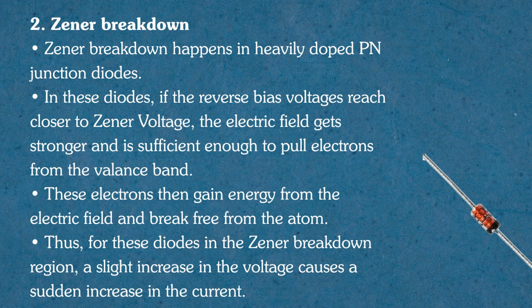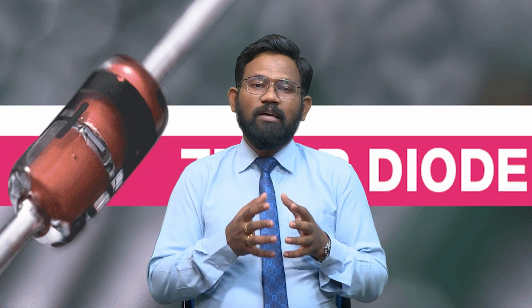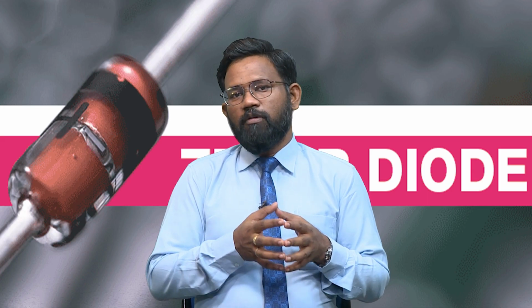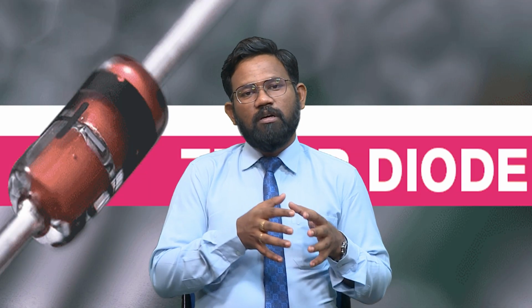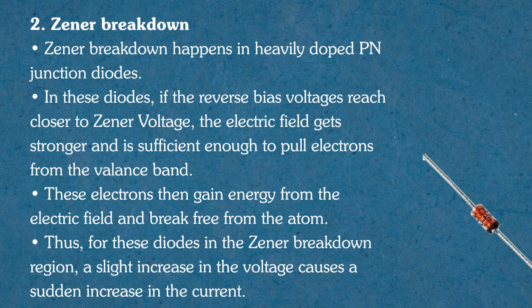The Zener breakdown happens in heavily doped p-n junction diodes. So the basic difference between the p-n junction diode and the Zener diode is the doping level. In a Zener diode, the doping level is very high, which allows it to work in the reverse bias condition. So in these diodes, if the reverse bias voltage reaches closer to the Zener voltage, the electric field gets stronger and is sufficient to pull electrons from the valence band.